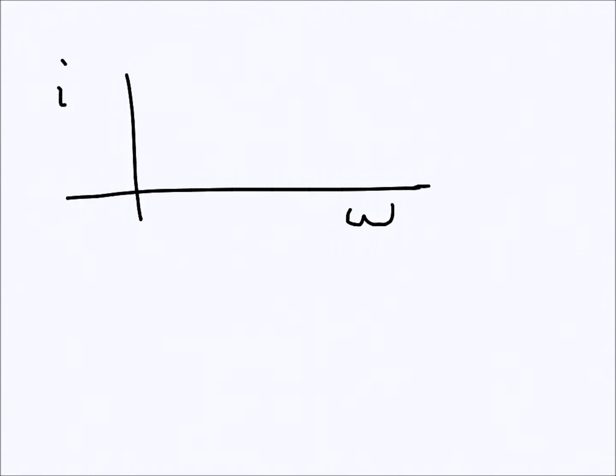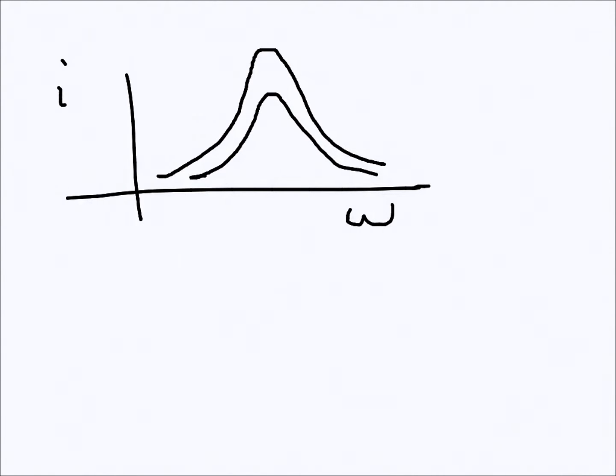So this goes something like this. If we change the frequency and plot the current for various frequencies, the plot will be something like this. I will draw maybe another one, and this one is for a greater R, so R is increasing this way. The higher the R, the peak is decreasing and current everywhere is decreasing. And this one is the frequency when it is not changing, since this is happening only at R. So this is the resonance frequency.